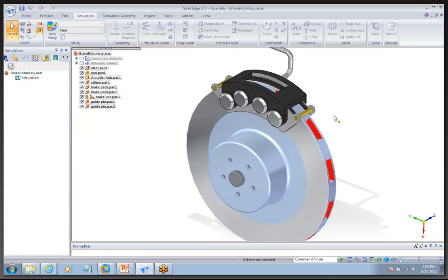So I use that potential energy, which is just the weight of my truck times the height of the hill, and I have to absorb 85% of that with my brakes. Because you've got losses with friction and whatnot, 85% of that energy has to be absorbed by the brakes. I've got 4 brakes, so I divide that by 4. I've got a spreadsheet, I calculate that out, and I get about 2,400 watts. So this brake has to absorb 2,400 watts of energy, and I want to see how hot it's going to get.